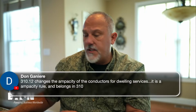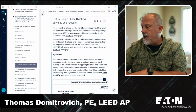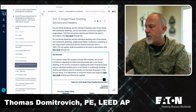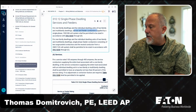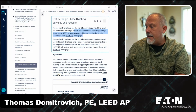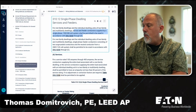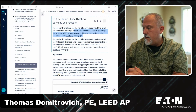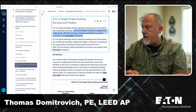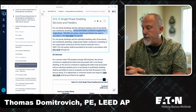So 310.12 says, for one family dwellings and individual dwelling units of two family and multifamily dwellings, service and feeder conductors supplied by a single phase system shall be permitted to be sized. So it's how to size service and feeder conductors. For one family dwellings and individual dwelling units of the two family, single phase feeders consisting of two and so on shall be permitted to be sized in accordance with 310.12 A through C.